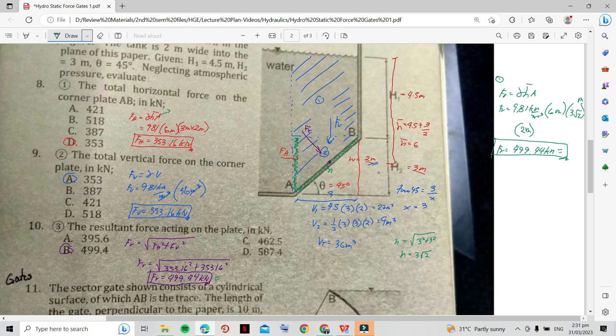By solving the vertical force and horizontal force, you can solve it with trigonometric functions because you already have your triangular loading. The angle considered is 45 degrees. So this is your resultant force, vertical force, and horizontal force. When you solve for the vertical force, you have the resultant force times sine of theta, and the horizontal force is equal to the resultant force times cosine of theta.